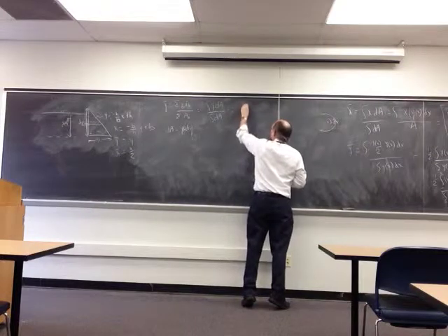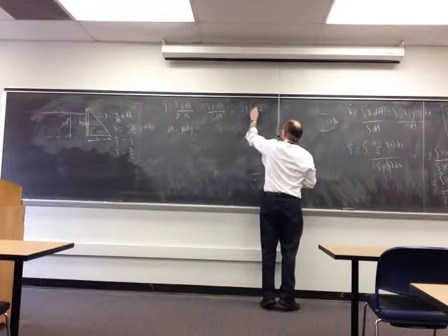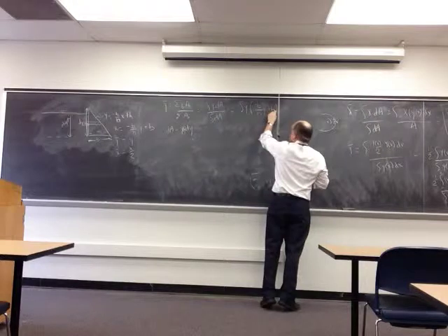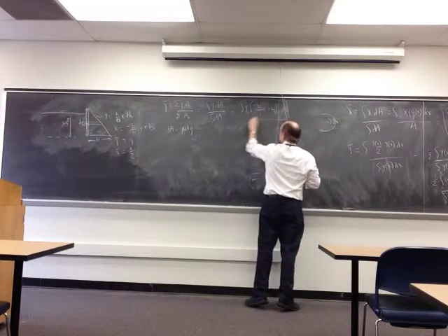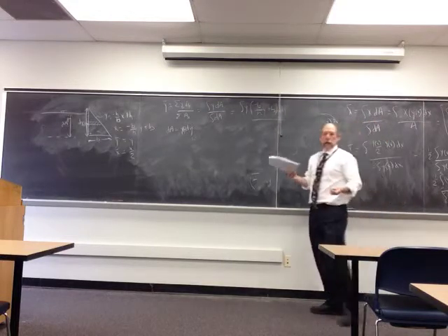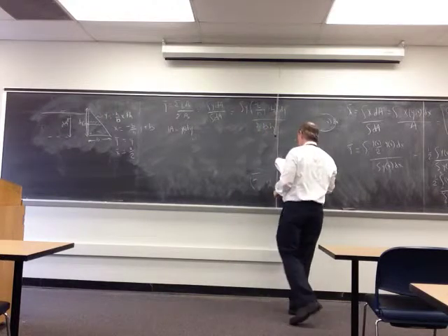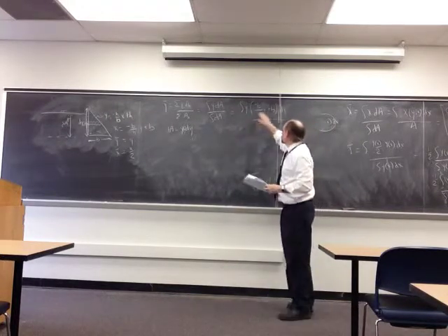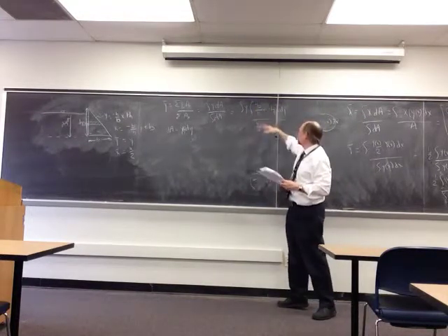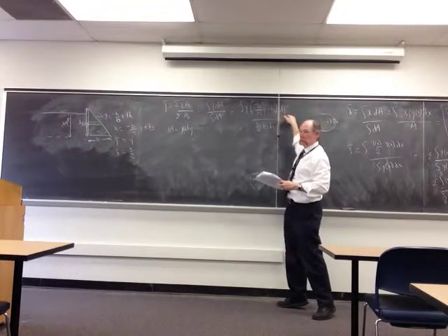So this becomes the integral of y times x of y, which is minus b over h times y plus b, dy. And the integral of dA is the area, and the area of a triangle is 1/2 the base times the height. So you multiply this through, take the integral in parts, and since b and h are constants, you have minus b over h y squared plus b y times dy.